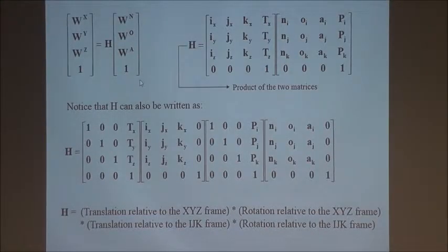So, therefore, the relation between wx, wy, wz compared to the end effector location, or the end of the total translation and rotation, H is the transformation matrix. And it's going to be multiplication of those 2 respective matrices of their own.